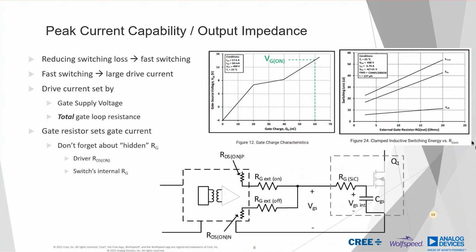In order to complete the switching transition, the gate driver needs to deliver enough charge to the gate so that the switch is fully on. Speeding up the switching means delivering this charge faster, and since current is charge versus time, faster switching means more gate drive current. That is a reasonable simplification outside of the Miller plateau.